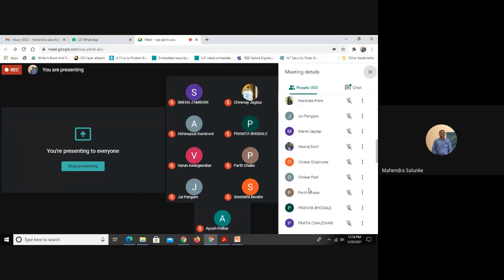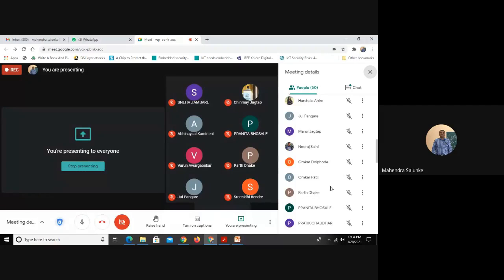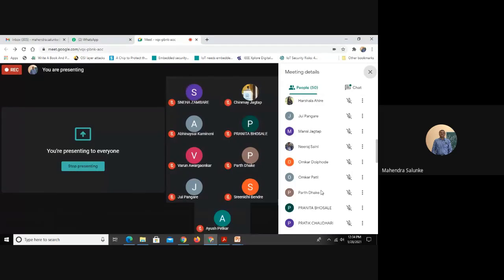But in case of read operation, this signal will be indicating that whatever the requested data, it is successfully placed on the data bus, and the processor can read that particular data after receiving this ready signal.